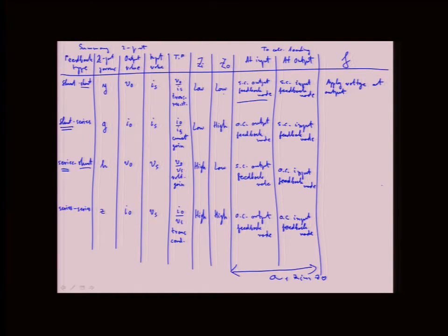Current, right? So if that two-port feedback consists of a current-controlled source and some parallel impedance, how do you extract the value of just that current source? Again, what I have is I have this, right? Y11F. And then here I have Y12F times V out, right? So I really am interested in this quantity over here because that is F, right? So how do I, by applying voltage to the other side, right?